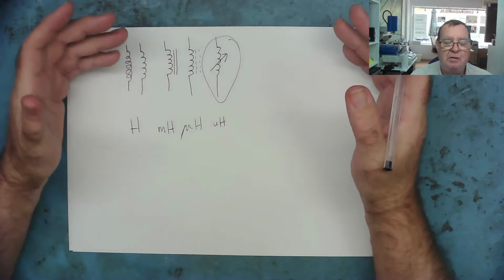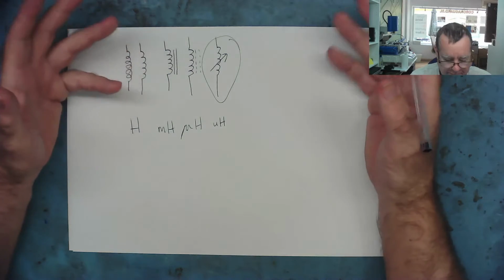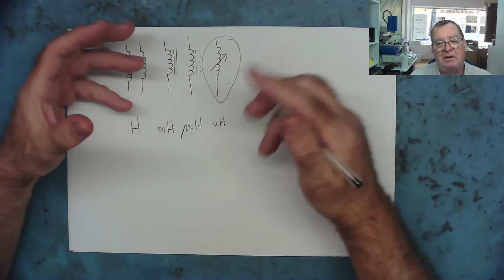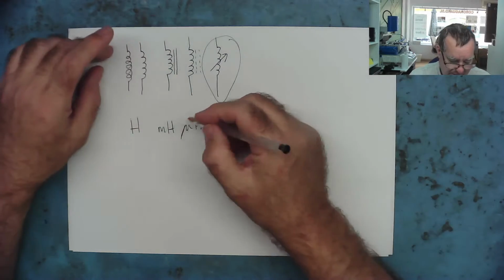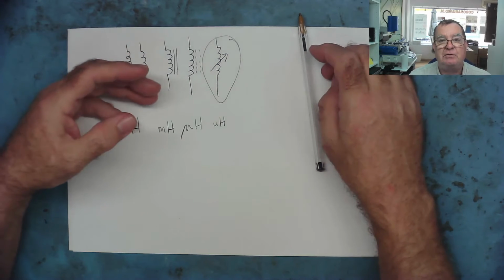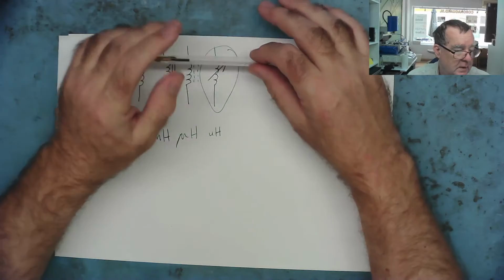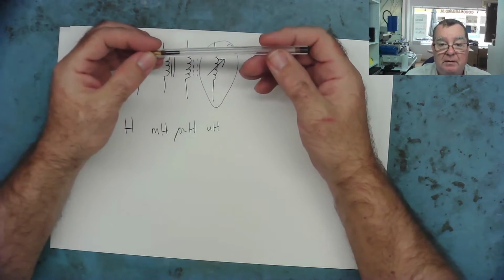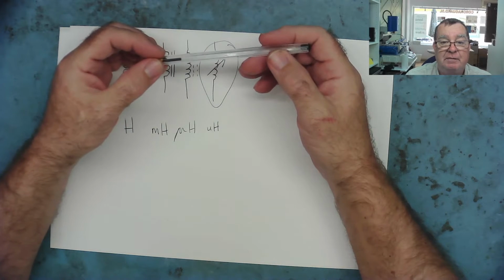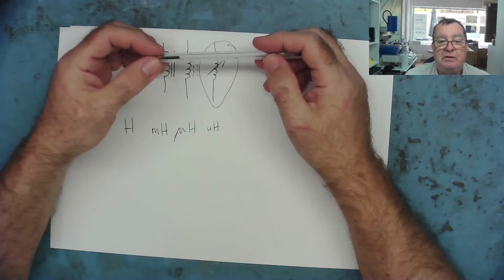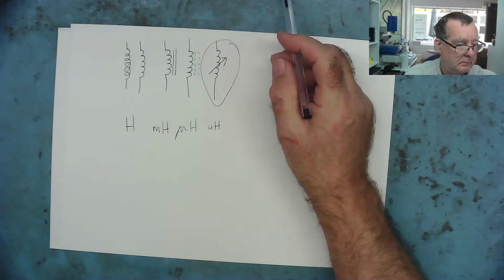Inductors don't have any other type of rating like voltage rating. There will be a maximum current that the inductor can pass, but generally speaking, the henries is the only rating you actually see on an inductor. An inductor can store energy in its magnetic field very quickly, and likewise it can discharge very quickly. This feature is important in many modern circuits where the inductor is used effectively to regulate voltage.